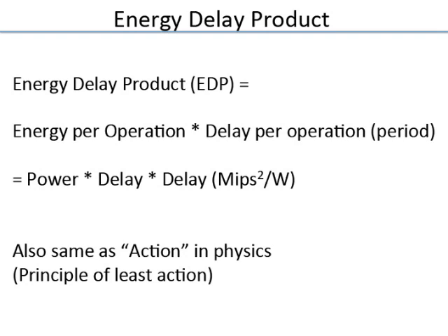So then you might come up with a metric ED squared, not E times D, but E times D times D, or E times D times D times D, and so on. So it depends on what you emphasize. People also have energy delay squared and so on. But in the absence of anything, if you are just looking at ways to compare designs and the efficiency of designs, you would use the energy delay product as a way to compare designs.